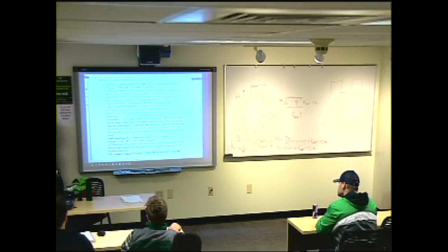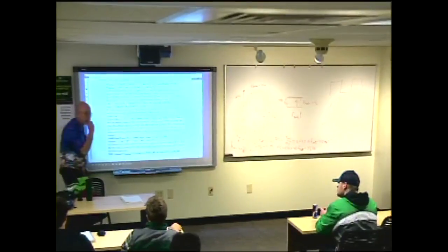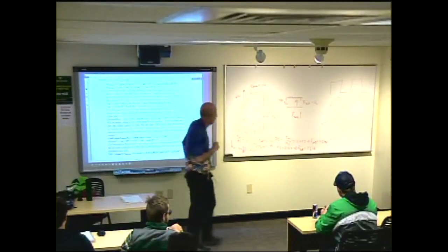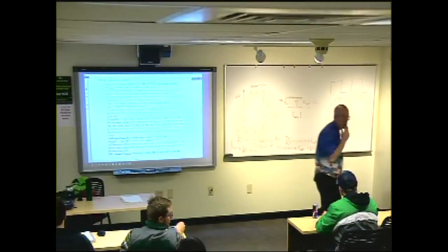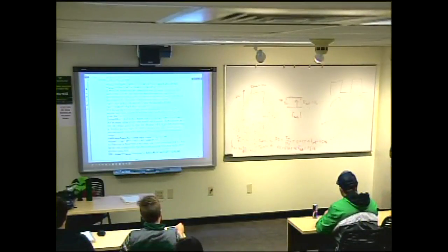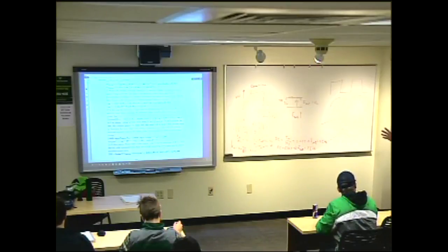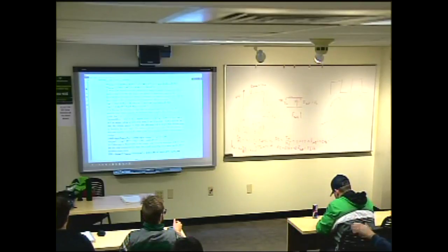Okay. Any other questions? Yeah, Gitesh? So going back to this rise time and fall time, the bigger the bandwidth, the better. The bigger the bandwidth, the less it will distort your signal. But if you go by our noise analysis, the lesser the bandwidth, then it's better. Right? That's right. Engineering is about trade-offs.